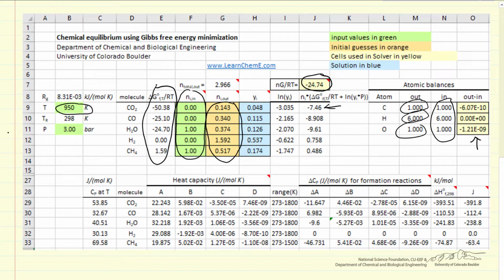So the big advantage of using this Gibbs free energy minimization is that we can do the calculation. If we have 5 reactions, we add 2 more species. The calculation doesn't become more complicated. We just have another value or 2 that we add to the Gibbs free energy, and if we have other elements, we add those also. And we use the exact same approach, whereas we get more reactions solving those equilibrium expressions. With multiple extents of reaction it gets much more complicated.